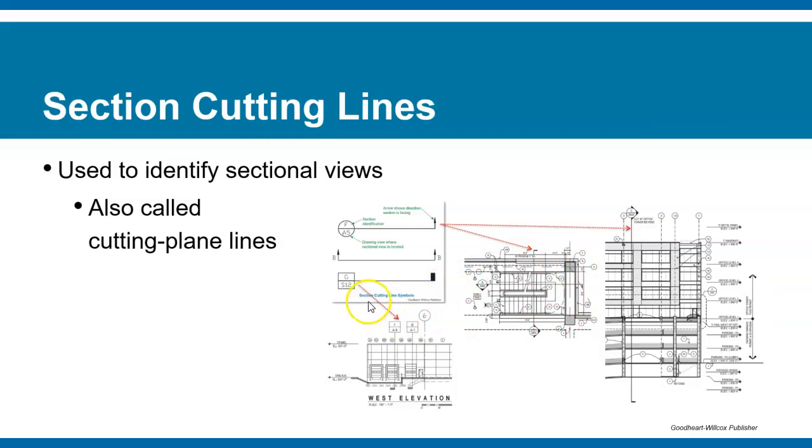And with the note over here on this side telling you that you could see whatever that slice looks like, the details on drawing G on page S12. Here, you'd see it on drawing F on page A5, or section F. And the arrow is the direction of the section view is facing. See? Same thing.